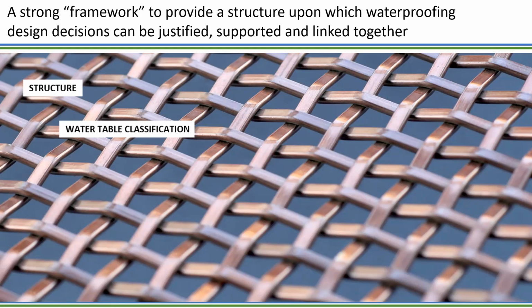of climate change. So I need to think about that, because if we're going to build a basement and it's a new build, we're going to dig a big hole and we're going to build the basement and we're going to backfill it. But what happens if we dig that big hole and the water table's 2 feet below the surface of the soil? Well, we're trying to build in a duck pond, aren't we? So it's important to consider that kind of thing as well.